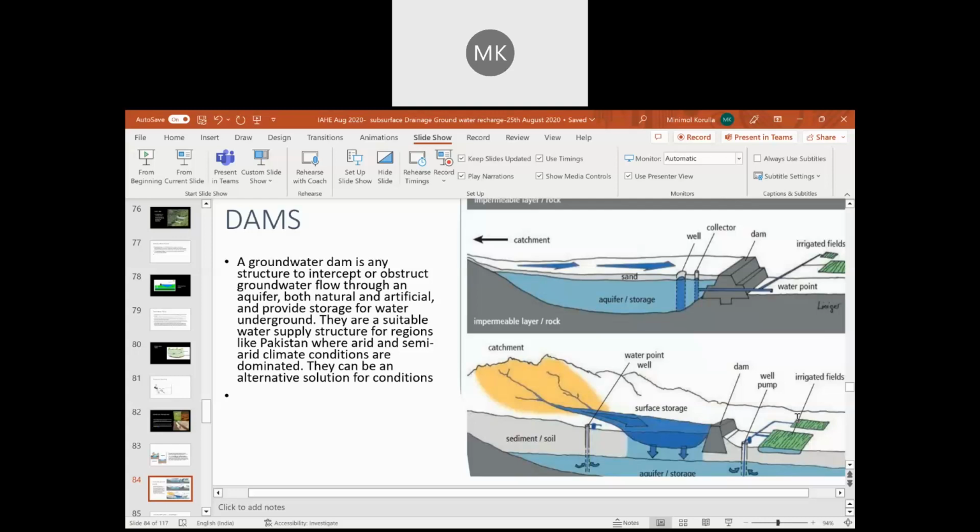And for the prefabricated vertical drains, what the specifications are and how it can be designed, there are different IRC codes available. MORTH also, the 700 series, is speaking about the PVD specifications. And there are two Highway Research Board documents, IRC HRB 13 and IRC HRB 14.